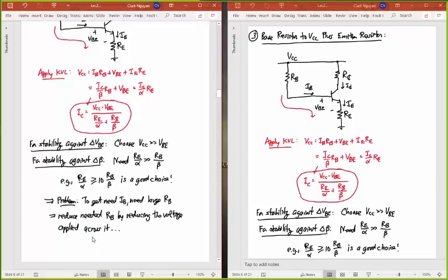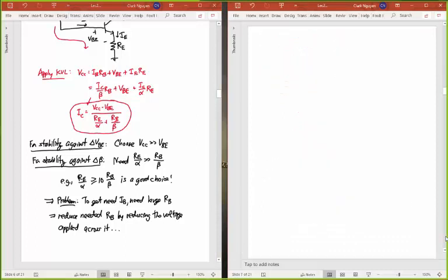And so this now leads us to finally the standard way that people will bias up a bipolar transistor circuit if it's a discrete off-chip circuit. There'll be different biasing techniques for on-chip circuits. But right now, at least, this is our standard parameter-independent biasing that you will use time and time again in this class, especially for your design labs that are coming up after Lab 4. Okay, so this is standard parameter-independent biasing.